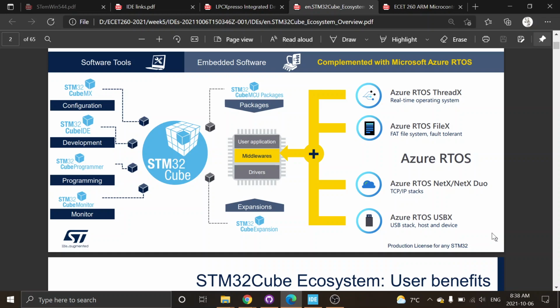And so that does everything that you're kind of used to as far as graphically going and selecting everything. It does the same thing, generates example code. But you need to use it with another compiler. So it generates all the code, but it doesn't compile. That's why some of you that fired up CubeMX, we were stuck. We couldn't go farther. You needed the Cube IDE. So CubeMX will generate this code and generate a project for you.